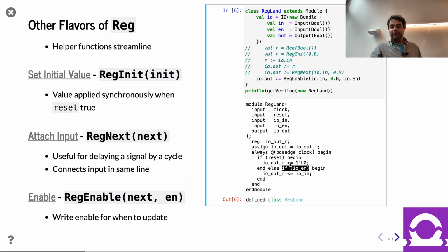But like I said, it's not a course on Verilog, it's a course on Chisel. And you see in Chisel, whatever you want to do with registers, we have available, right? We have vanilla Reg, default value. A lot of times maybe you find RegNext very convenient. But there's nothing wrong with using Reg. If Reg makes sense for you, or especially RegInit, those are all great. Cool. Questions? Yes?